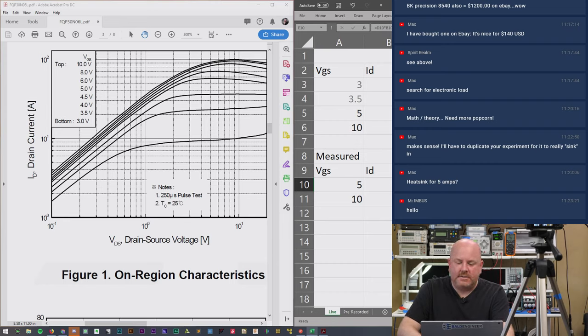And so here's what we can see. At 5 volts at a VGS, like coming straight out of an Arduino, this transistor will have an on resistance of 31 milliohms and dissipate 780 milliwatts. If we double VGS, then we get a big drop in power dissipation.